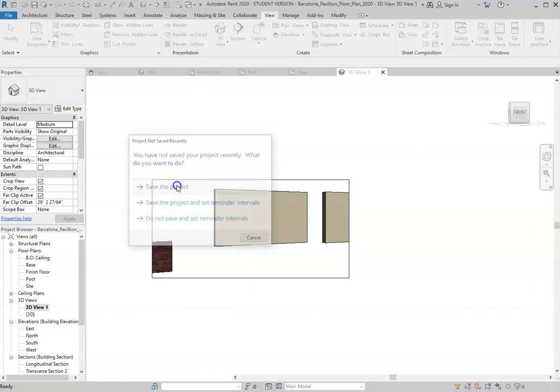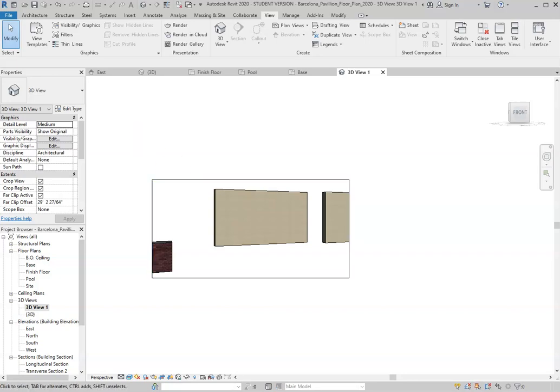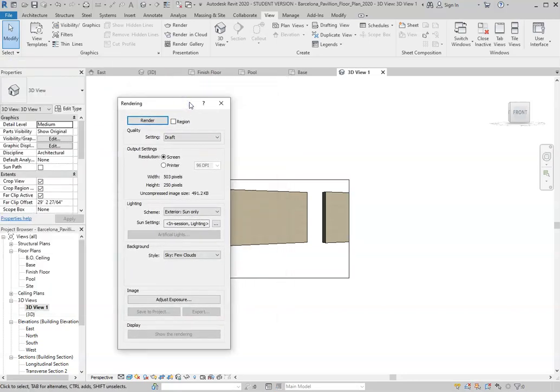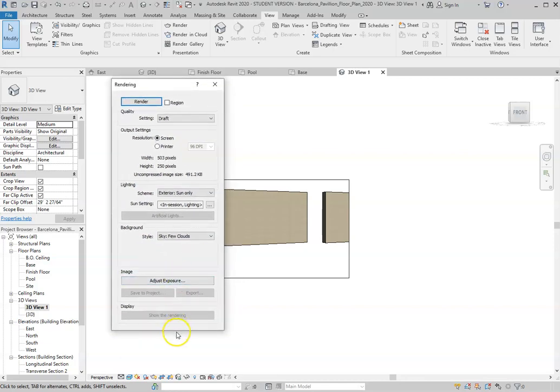Click on render. This we could always save as we go, and then this rendering box shows up. So we will dig more into this later. Just to get things started, though, the box will render the region. That would be just what's on the screen, actually, or we would choose a region, and that's just if you have a big rendering and you only care about one part of it. If you're just struggling to get the water right, for instance, you don't need to re-render the entire shot. You could zoom in on a region and just redo that until you get it right.